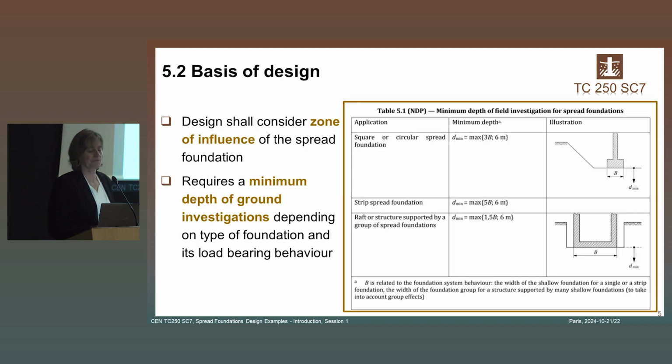Another issue which has an impact on the quality of the design and is related to the geotechnical categories, which we heard about earlier this morning, is that the zone of influence needs to be considered for the specific type of structure, in this case the spread foundation. So the spread foundation has a zone of influence beneath the foundation base, where it transfers the stresses from the structure to the soil.